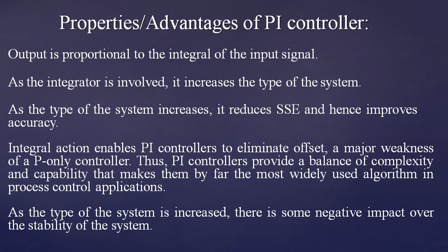As the type of the system increases, it reduces the steady state error and hence improves accuracy. Integral action enables PI controllers to eliminate offset, a major weakness of a P-only controller. Thus PI controllers provide a balance of complexity and capability that makes them by far the most widely used algorithm in process control applications. As the type of the system is increased, there is some negative impact on the stability of the system.